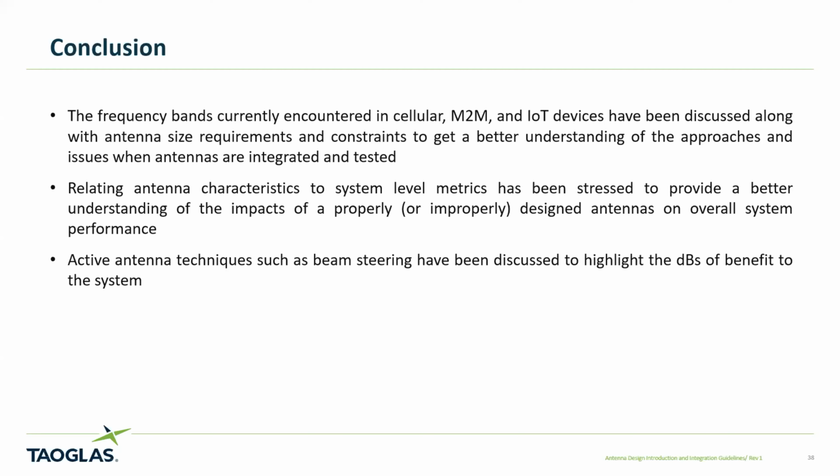Well, I don't have a straight answer. I can add a little bit to that, though. When I was showing the data on that test house, we were doing a lot of work on Wi-Fi 802.11ac, and 4x4 antenna systems on an access point. What surprised us, working with the rest of the industry, the radio chipset and baseband people, was that I was walking in around the 2013-14 timeframe thinking a 4x4 antenna system was operating in MIMO mode most of the time.